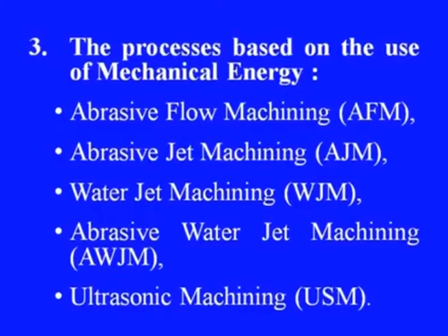These processes include abrasive flow machining, in short known as AFM, then abrasive jet machining, also known as AJM, water jet machining, WJM, which we can say is completely the use of mechanical energy, conversion of mechanical energy, and then abrasive water jet machining, which can be considered a hybrid of water jet machining as well as abrasive jet machining, and then ultrasonic machining, which is by far a very popular process as far as the machining of brittle materials is concerned.